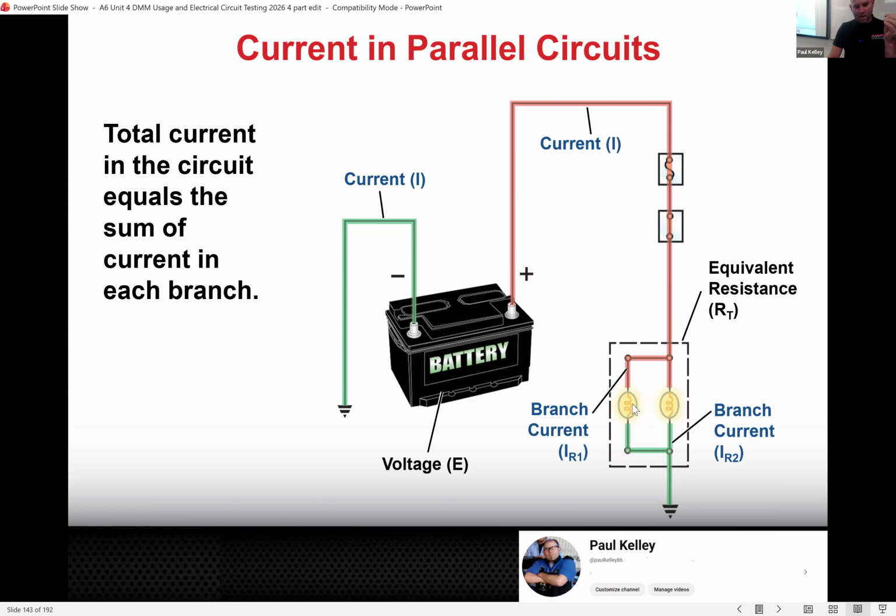12, exactly. So if you have 8 cars here and 4 cars here, that means 12 cars came down this main road, right? That's the visual, that's the application of Ohm's law in amps in a parallel. See how that's so different than series? Series was the same everywhere, it's only one lane. Once it's multiple lanes, you got different amounts of amps flowing on different points of the circuit, but all the individuals would total to become the main road, right? That's the total amperage is equivalent to all the individuals. Cool, that's kind of the point.